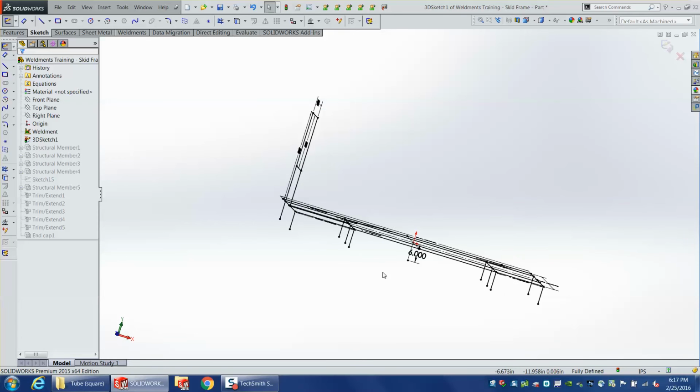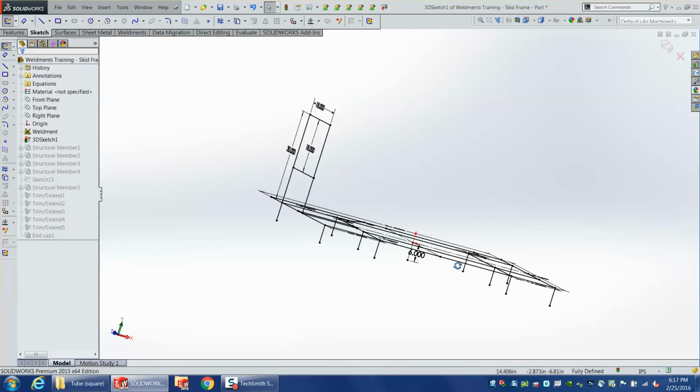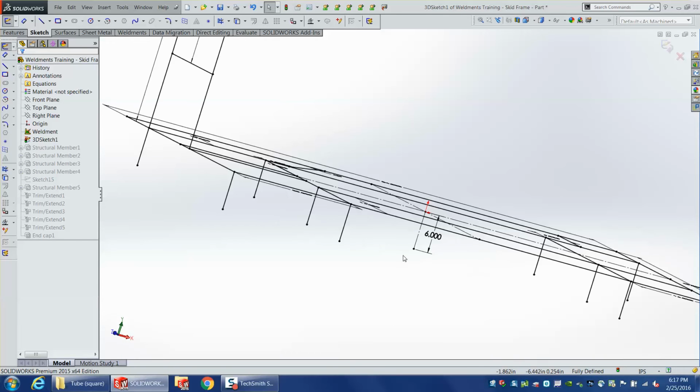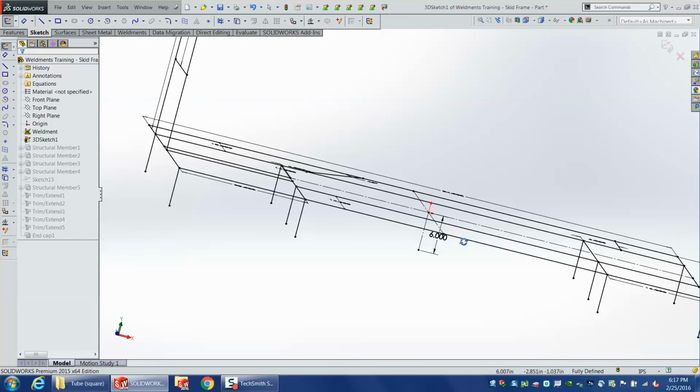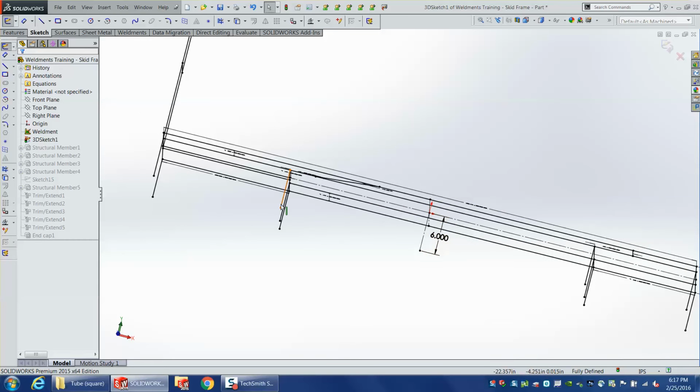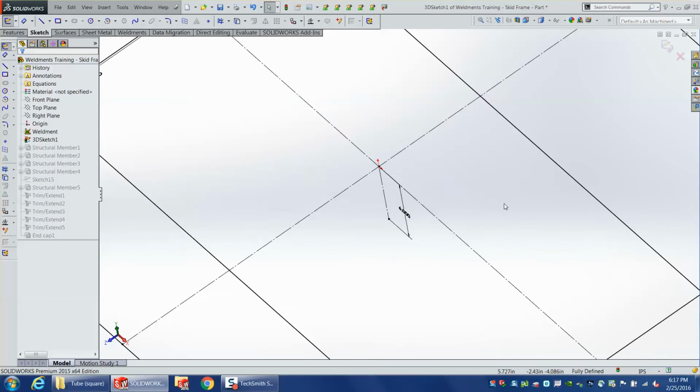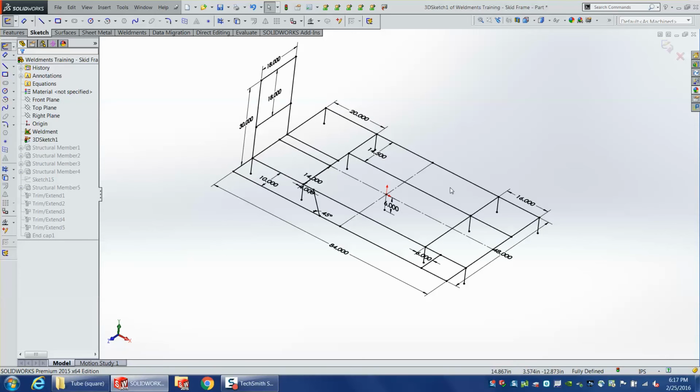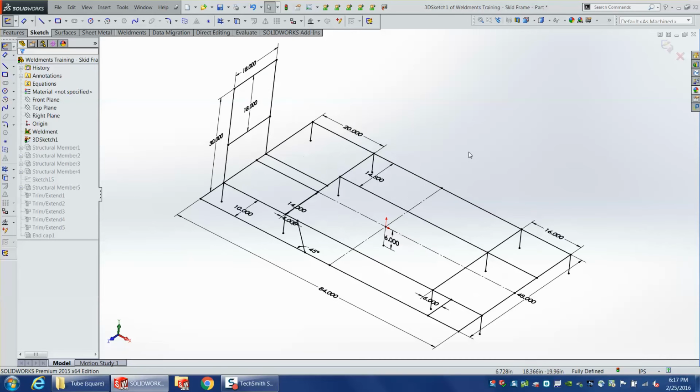I only have one dimension for the length of all my feet. They're all set equal to that one. Another principle is use least powerful relations that you can. The hard thing about 3D sketches is it's a pretty complicated thing to solve, and it's a pretty complicated logic puzzle to go through and find where the mistake is or where the over definition is happening.